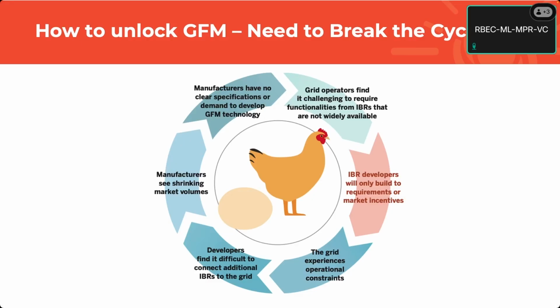Okay, and that one shouldn't be a problem for battery cycling, because if you plot the state of charge, even if you're going rail to rail for a little bit, your state of charge isn't changing on a big battery. If it was a capacitor, that would be different, but it's a battery with an hour or two of storage, so state of charge is flat through that. And that's apparently what the batteries don't like, is if you're moving your state of charge all the time. Yeah.